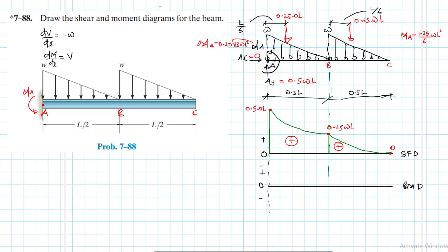What we are going to do is imagine you do a section of this beam to the right of a very, very small infinitesimal part. If you did a section there and then checked the internal forces, you are going to find a moment in this direction, of magnitude the same as MA.